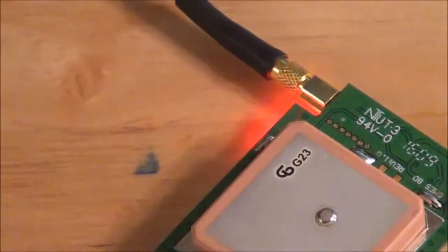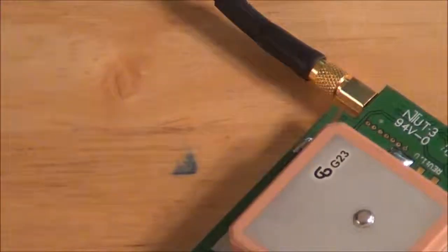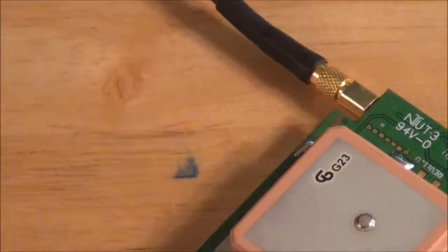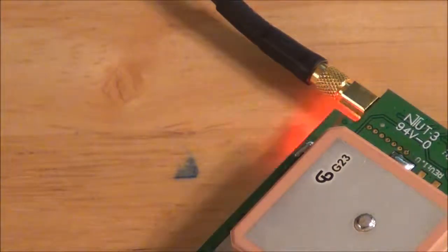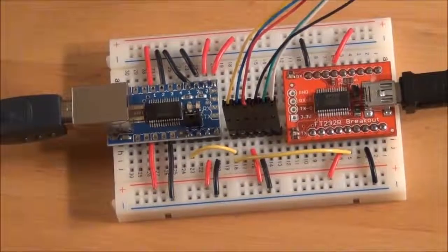With the PMB688, there's an LED that blinks on the back of the board, and that's while the unit is getting its GPS fix. Depending on how long it's been since the unit was turned on last, if it was turned on more recently, it'll take less time. Once the PMB688 has enough satellites tracked that it perceives that it has a legitimate GPS location, then that light will go solid, and then you know you're good to go. So let's go ahead and take a look in the Device Manager in Windows for how these two boards appear.